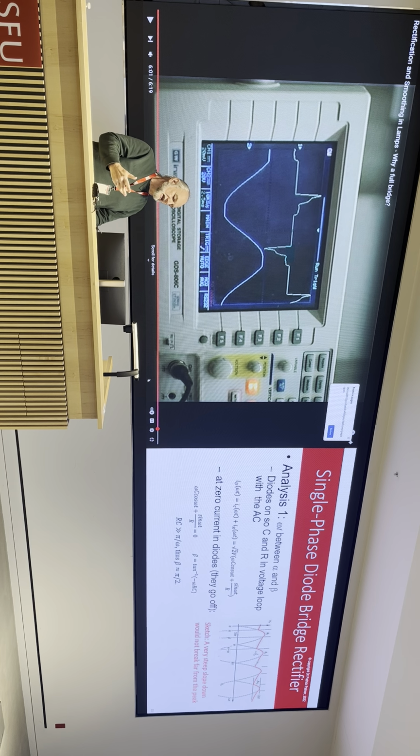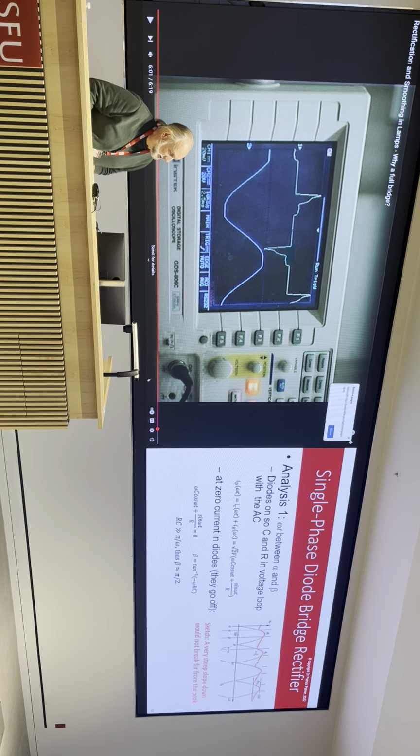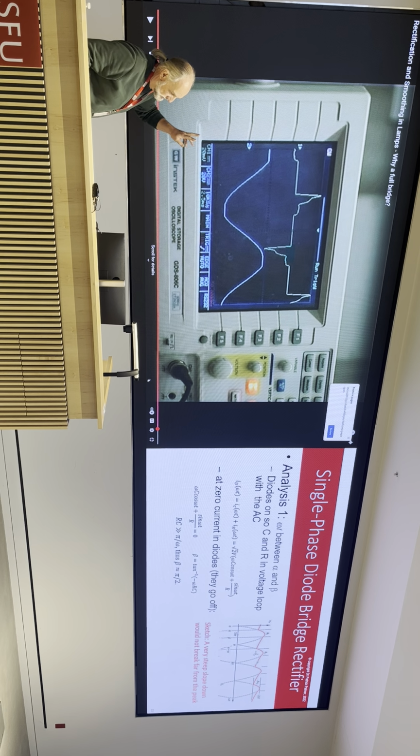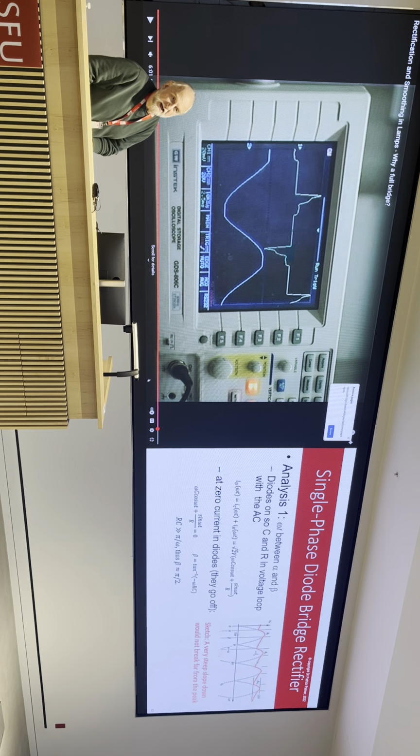Why do I mention that here? I want you guys to go with the maths. Don't say, oh, that can't do that. Think about what the maths is telling you. You've sketched it, you've simulated it, whatever you've done, think about what's happening. So again, that's a reason for having a smaller capacitor, because then your spike current is smaller, which is nicer to your diodes. You're likely to get a longer lifetime.